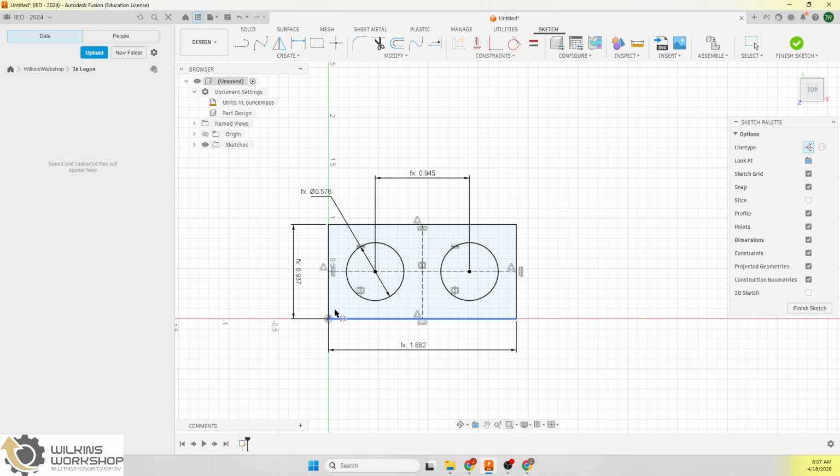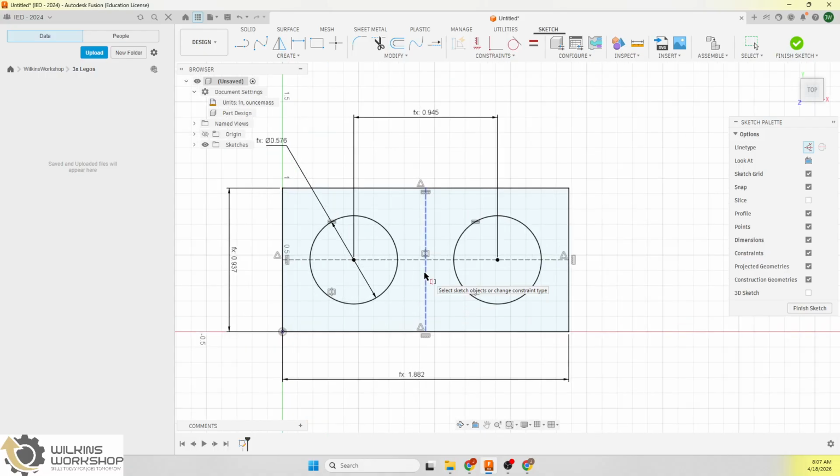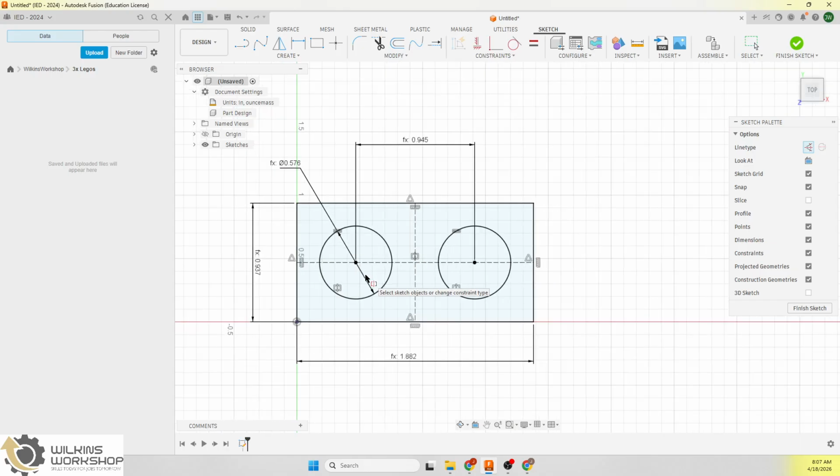Well, remember, we removed a kerf from the outside and the kerf from the outside. So the distance to the midpoint to the center is different than the distance from here to the outside, because there's an air gap that sits in there. So we always try to do something that's symmetrical about the middle, because we've removed material from the outside of the part. So it's always going to be smaller distances from the outside than it is from the things that are in the middle. So just kind of keep that in mind when we're doing our references.